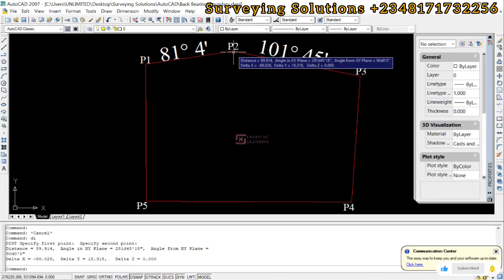You will find out that yes, the distance will still be the same, and then you might even convince yourself that it's actually the same line, no doubt, but the direction to which you have moved will now determine if the bearing would be the same as the bearing of that line, or plus or minus 180 will be affected on the bearing of the line.